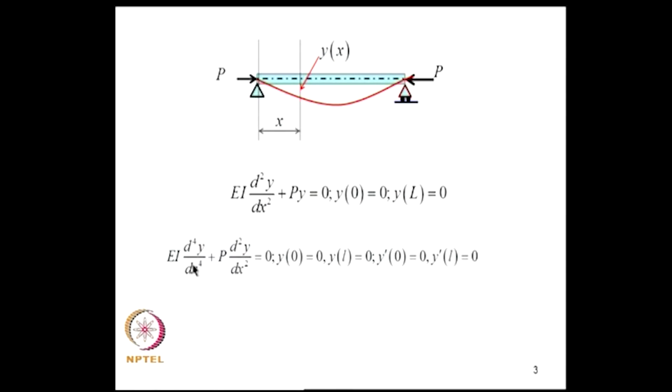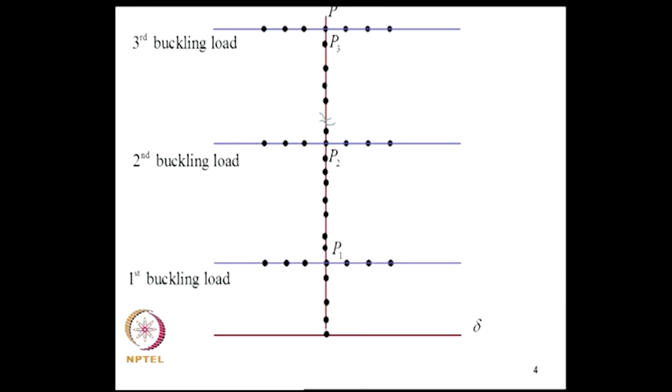order equation. I pointed out a couple of times that this term p y, that is p into this distance y, this force is computed, this bending moment is computed with respect to the deformed configuration of the structure, whereas while finding reactions and other terms associated with the equations of motion, we consider the undeformed geometry. That difference we have to notice, and we need to see later on how it manifests in a more generic formulation of such problems.